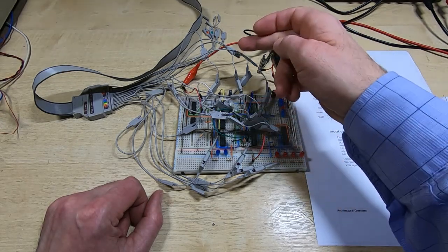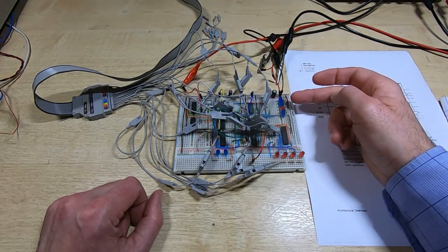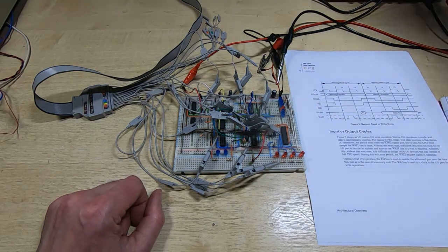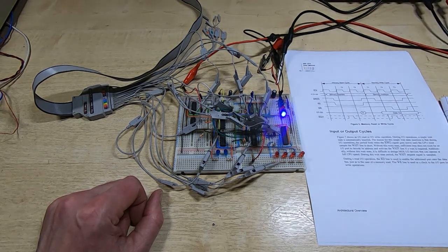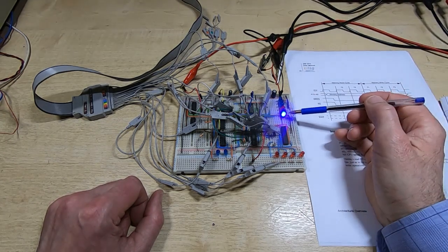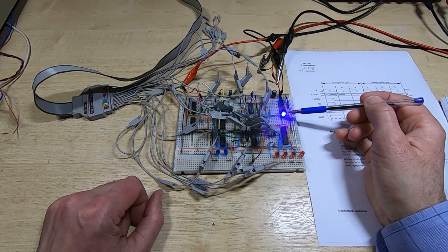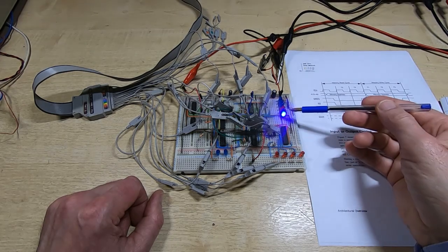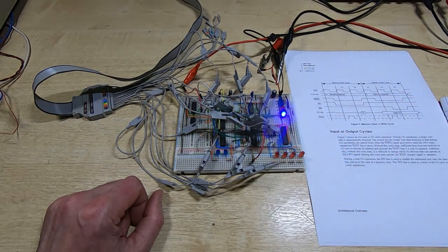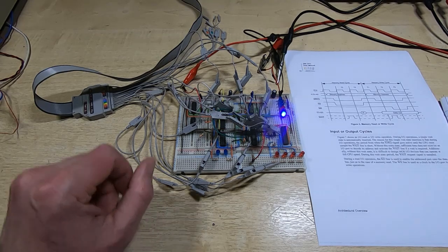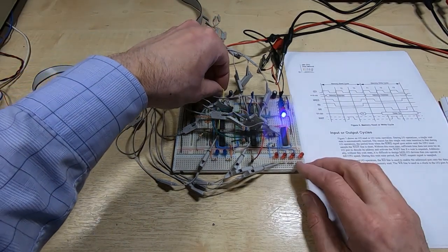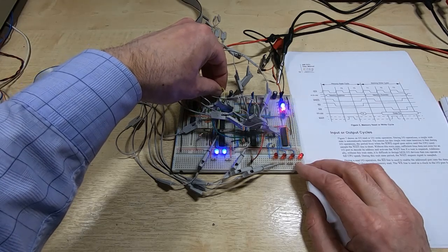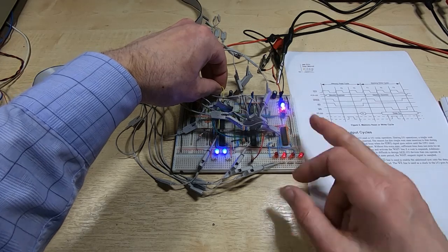So I've got the clock set to 0.5 Hz, which should be slow enough for us to see what's going on. So we'll power this circuit up, turn on the signal generator. The only LED that's come on so far is the clock LED going through to the counter, which in this case has gone high, but you should see that go low as part of the DMA cycle. So we'll start this running. We'll take the DRQ line high. So you can see the process is now running through.